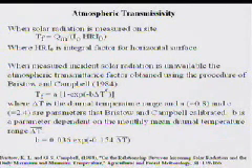When the measured radiation is unavailable, we go through this procedure that calculates the atmospheric transmissivity. The important quantity here is delta T, the diurnal temperature range. The assumption is that if the sky is clear, you're going to get a large diurnal temperature range.